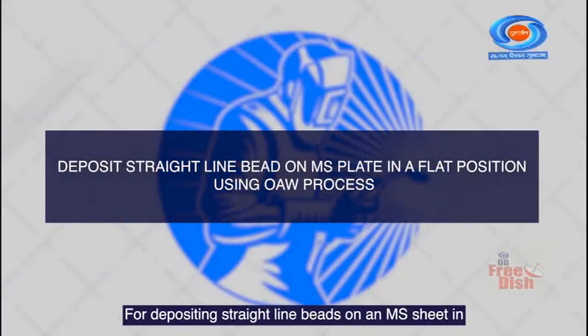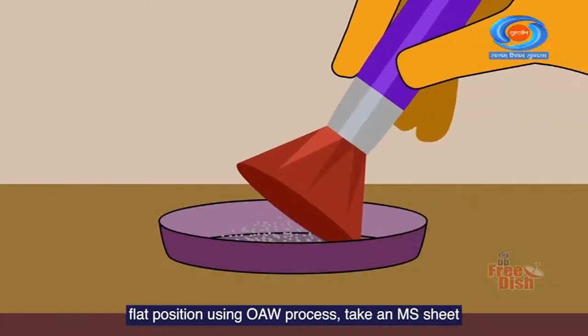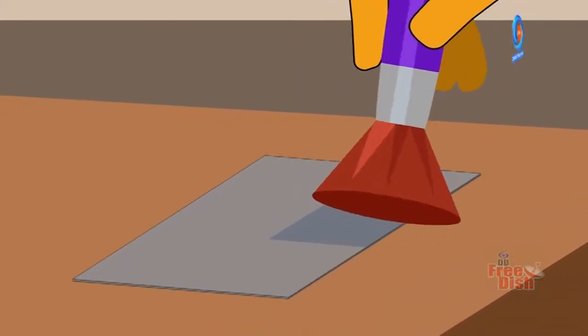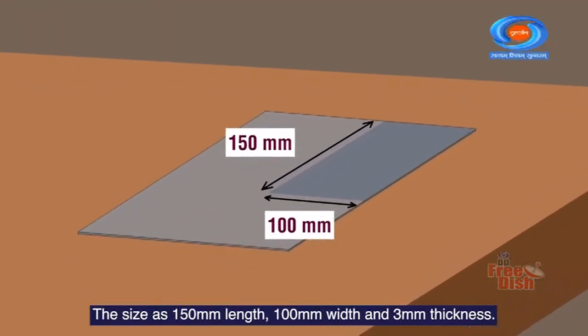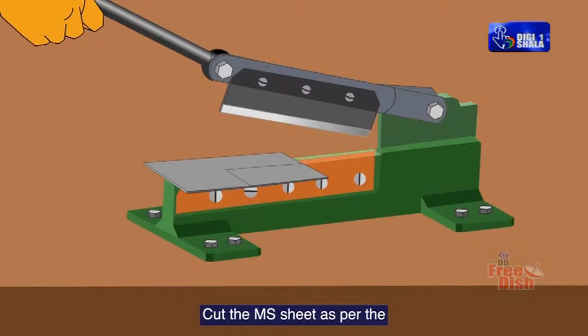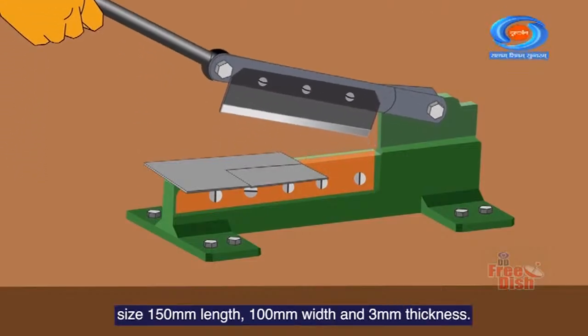For depositing straight line beads on an MS sheet in flat position using OAW process. Take an MS sheet and apply marking media. The size is 150 mm length, 100 mm width and 3 mm thickness. Cut the MS sheet as per the size 150 mm length, 100 mm width and 3 mm thickness.